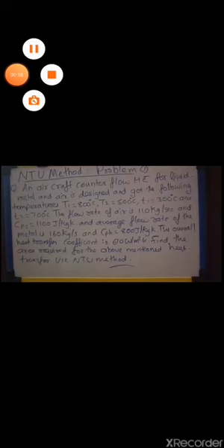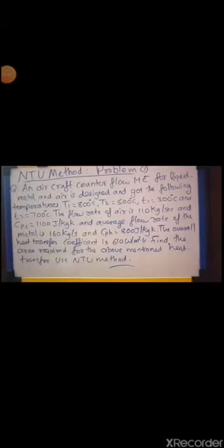That is capital T1 800 degrees centigrade, capital T2 500 degrees centigrade, small t1 300 degrees centigrade, and small t2 700 degrees centigrade. The flow rate of air is 110 kilogram per second, and CPC is equal to 1100 joule per kilogram Kelvin, and average flow rate of metal is 160 kilogram per second, and CPH is equal to 800 joule per kilogram Kelvin. That is, the mass flow rate and specific heats of both the fluids are given.